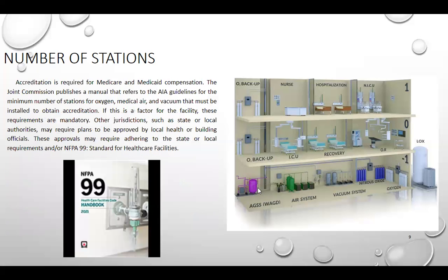So accreditation is required for Medicare and Medicaid compensation. The Joint Commission publishes a manual that refers to the AIA guidelines for minimum number of stations for oxygen, medical air, and vacuum that must be installed to obtain accreditation. If this is a factor for the facility, these requirements are mandatory. Other jurisdictions, such as state or local authorities, may require plans to be approved by a local health or building official.